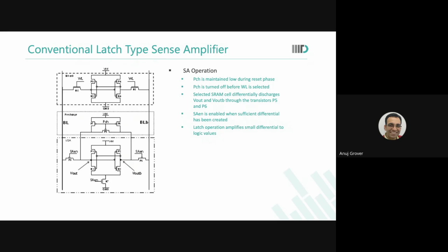So when you are drawing a sense amplifier layout, you have to be super careful about everything. We call that structural matching. So common centroid along with structural matching, that every metal for node A versus node B, I also ensure that it has the similar coupling with every signal that I could have coupling with.